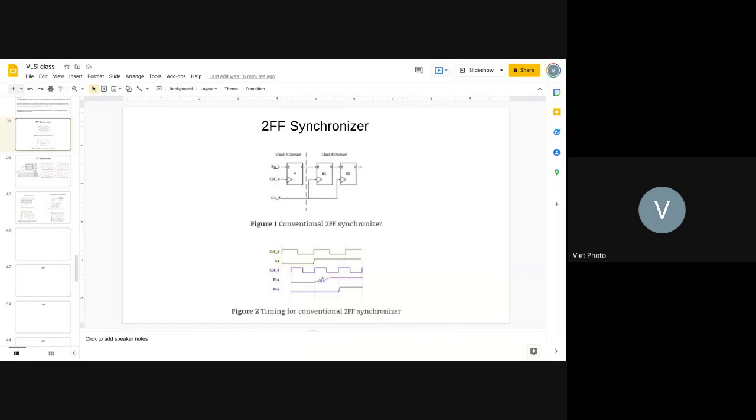That's why we don't want that to happen, right? But the number again, I think that is the probability for that to happen. The probability of that being infinite is only like one in a trillion cases, and we consider that as zero, right? So your question is, when we talk about metastability, we talk about it not being able to go to infinite. The case of infinite here is only a very rare case. But again, I talk about the theory and practicality, right? In theory, that's correct. In practicality, it is not.